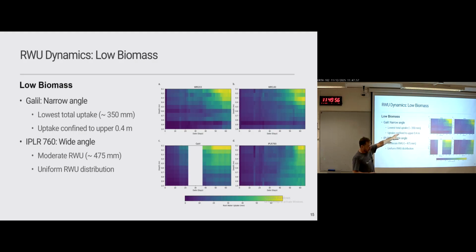If some area is dry, and for example here, this area is going to be dry because most of the water is taken up from here, but we have most of the roots here, still, most of the water late in the season will be extracted from a different location. This is important because in many ecological models, root length density is an important parameter responsible for transpiration.